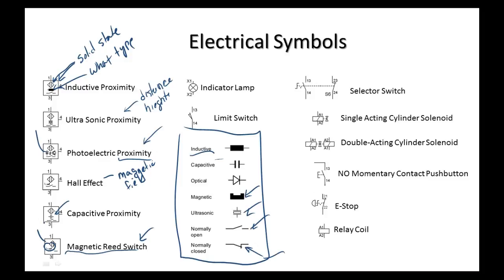And what it is, when the carrier gets into a long stretch and wants to go faster, it'll go past that magnet and speed up. Well, when it gets about 7 or 8 feet from the end of that line, it goes past the other magnet and slows down to make the turn. Well, it's probably a Hall effect. It's probably what they call a latch Hall effect, because the buffers sit there and cycle like 6 times. They've got those switches everywhere.